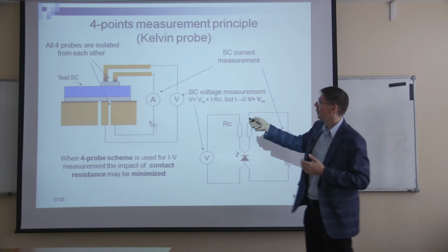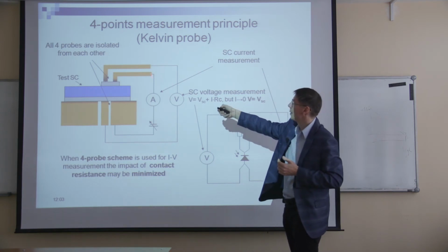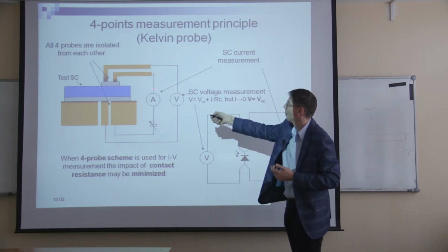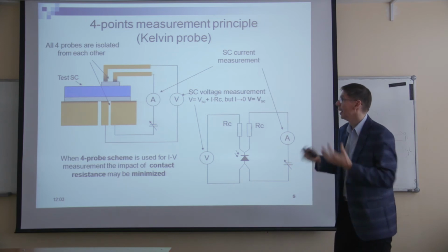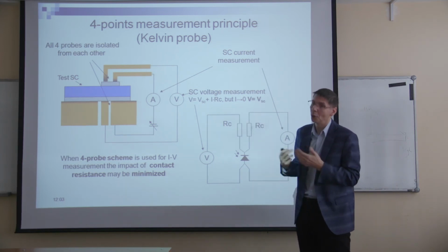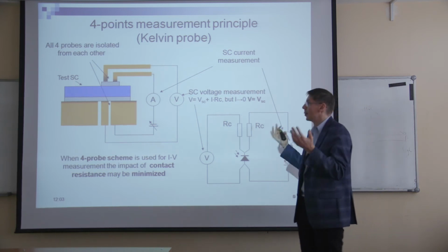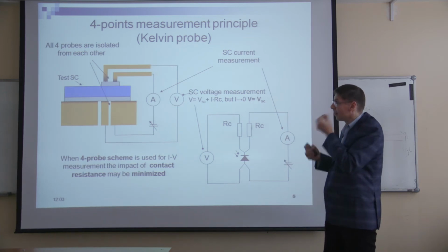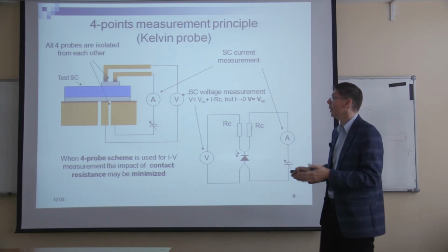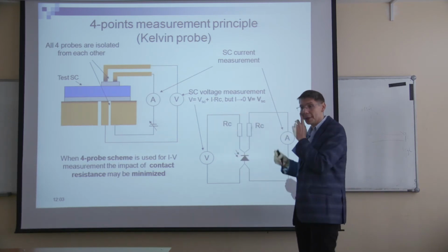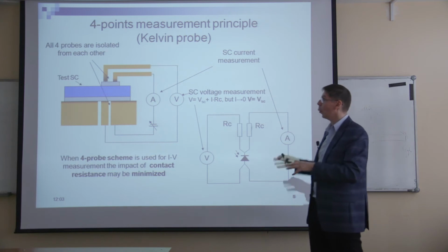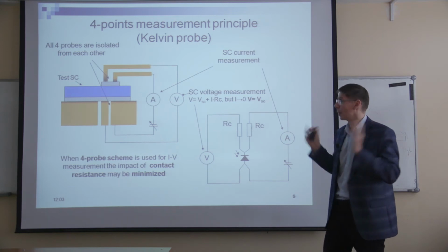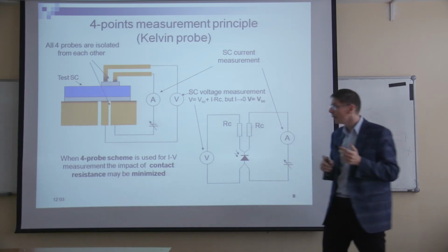You can simply check the resistance between two contacts. So we can disconnect, for example, from a source meter and check the resistance between two contacts. And if you have some reasonable value which corresponds to a real contact, some few ohms or even 100 ohms, it means that you are connected. So in this case, you are sure that there is no problem, I mean, for both pairs, for this and for this one. And there is no problem with the contact you can measure, is the first advantage.